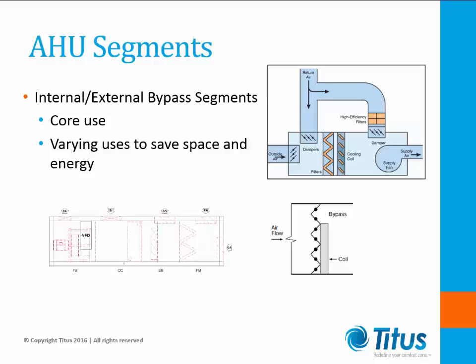The previous solution to this problem was to cool all the air down to overhead supply air temps and then reheat. This would then allow adequate dehumidification at warm enough supply air temperatures to maintain occupant comfort, but at a considerable energy cost. The solution to avoid using new energy for reheat is to provide a bypass. By cooling some of the air below dew point and then mixing it with return air to the desired supply air temperature, now the humidity is handled as well as the comfortable supply air temperature without using new energy for reheat.